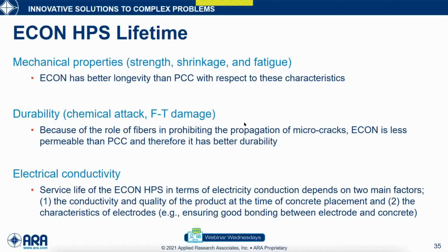Typically, fibers will reduce plastic shrinkage and drying shrinkage, and definitely will improve the strength of the material and keep the cracks tied together.